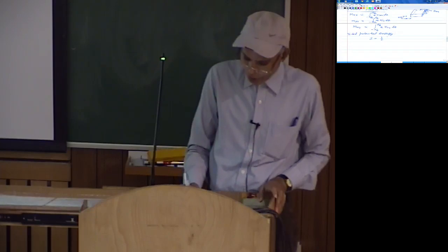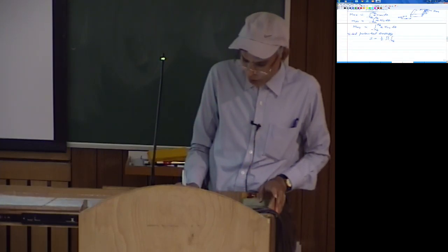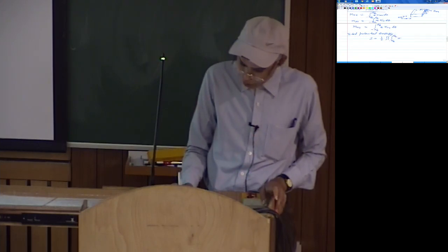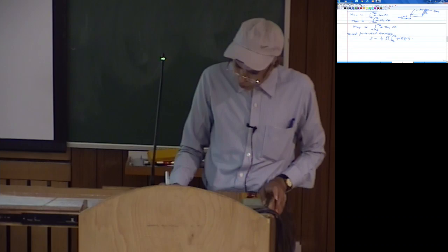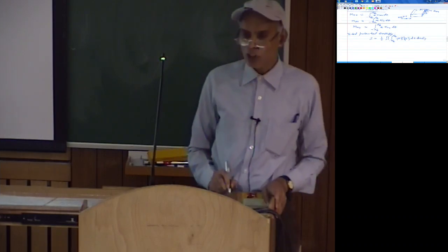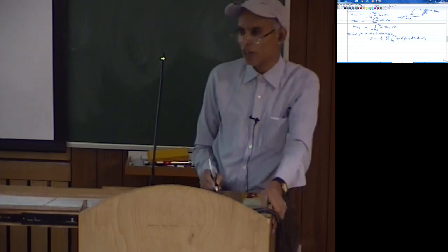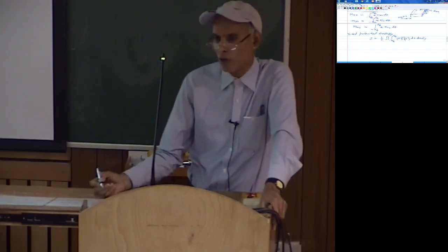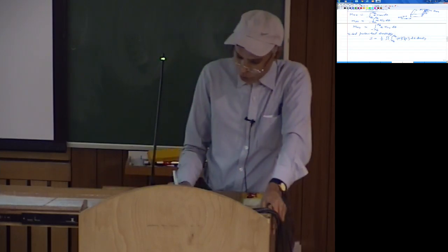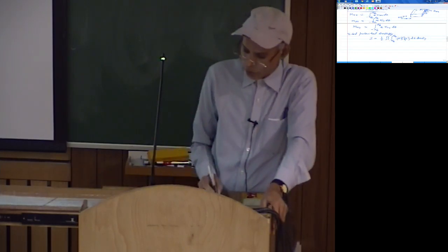So here we write the integration with respect to x, y, and the integration through the thickness, which is minus h by 2 to plus h by 2, and then as usual you write sigma transpose into epsilon, and then you have dz first, and then dx dy. So this is your strain energy. As usual, sigma xx into epsilon xx plus sigma yy into epsilon yy plus tau xy into gamma xy. That is the strain energy integrated over the entire volume.